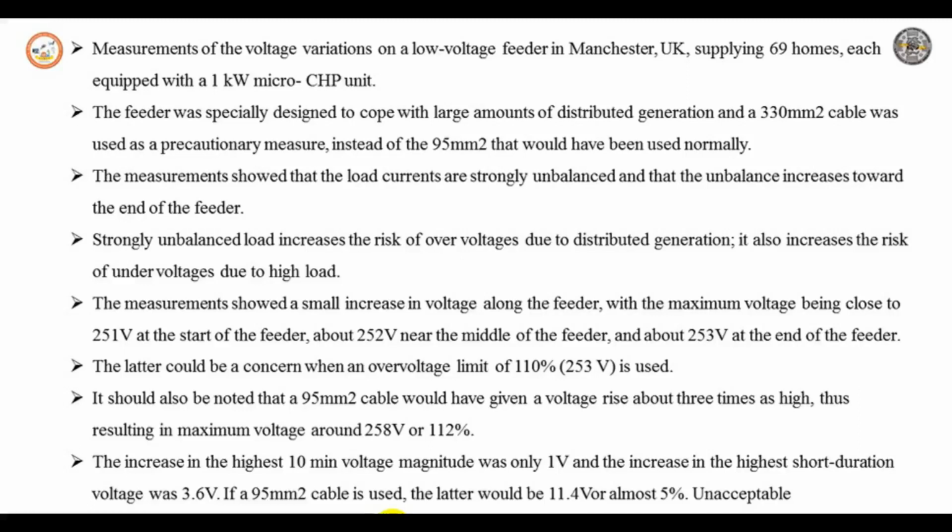So voltage magnitudes of up to 115.9% are possible. During this backup operation, to keep the maximum voltage below 110%, the hosting capacity should be as low as 23%.